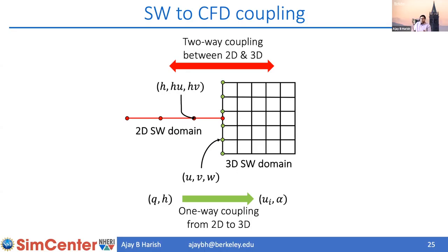So this is something that we understand is a drawback of the method, and we need to keep it in mind when we are choosing how much time we want to simulate and what our domain size is. A simplistic way of thinking about it is: what is my wave velocity, and how much time would it take for it to have a reflection and come back to the same surface? So this velocity would define how much time you can simulate for.